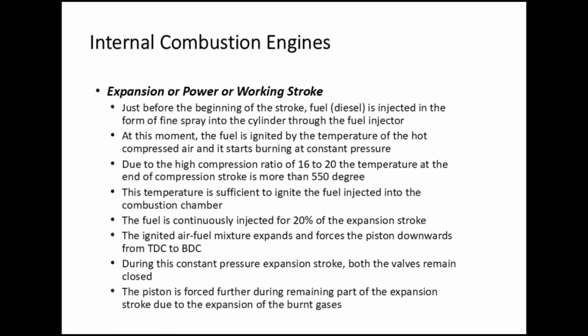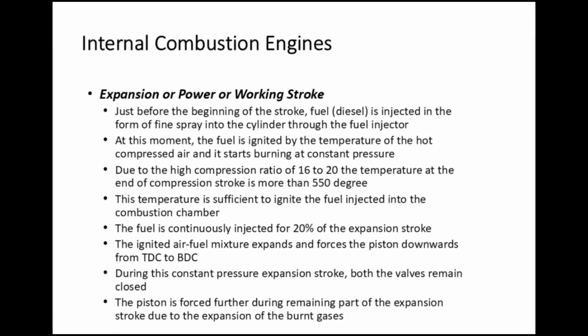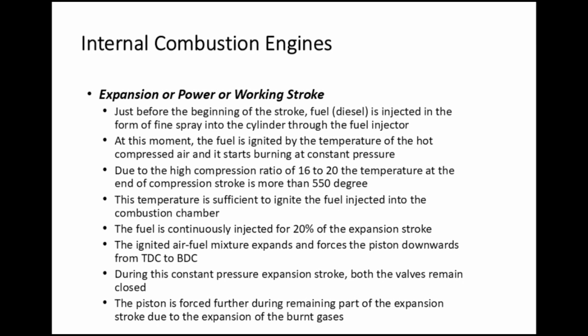Internal combustion engines. Expansion or power or working stroke. Just before the beginning of the stroke, diesel is injected in the form of fine spray into the cylinder through the fuel injector. At this moment, the fuel is ignited by the temperature of the hot compressed air and it starts burning at constant pressure. Due to the high compression ratio of 16 to 20, the temperature at the end of the compression stroke is more than 550 degrees. This temperature is sufficient to ignite the fuel injected into the combustion chamber.